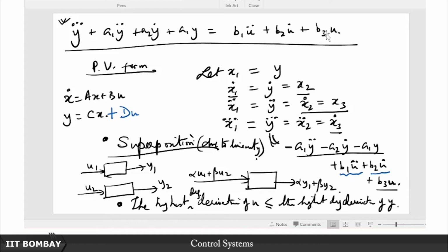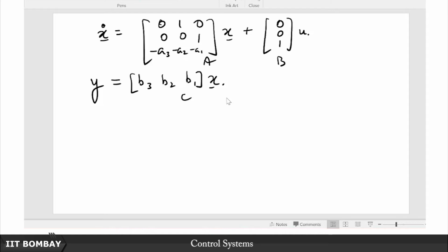But if you are really someone who is into deriving a state space representation of a differential equation quickly, then it seems that this is the most convenient one of all after all, right. Whether I give you the differential equation or the states or the transfer function description, you see these are nothing but the coefficients of s, s squared, s cubed, and the constant in that transfer function, right. That is all that you are dealing with in representing it like this. So therefore this phase variable form is a particular favorite in some sense. So people are a little biased towards this phase variable form.